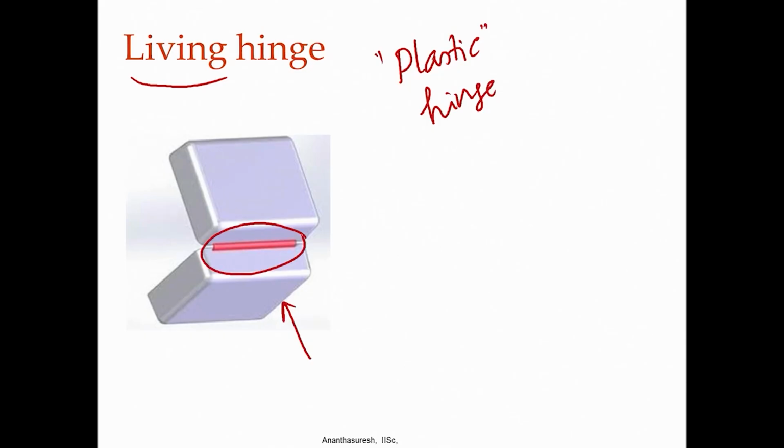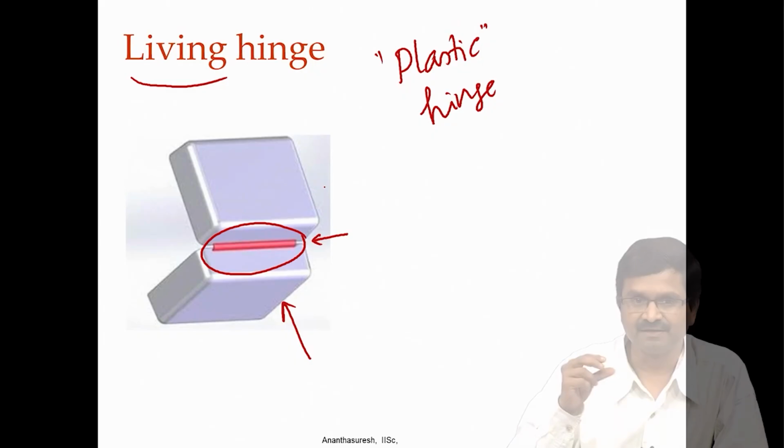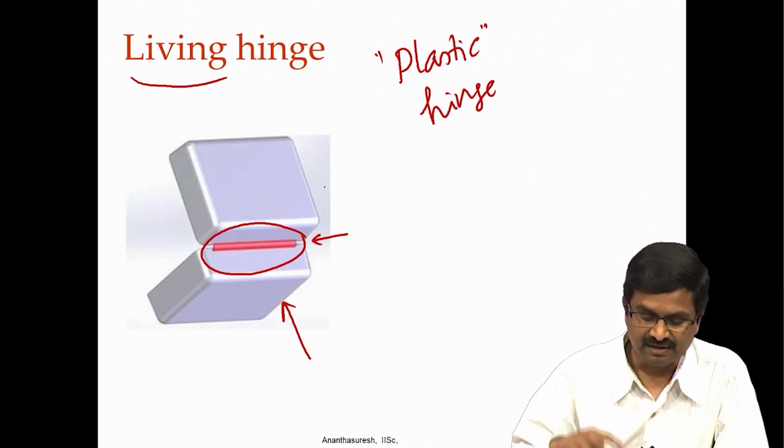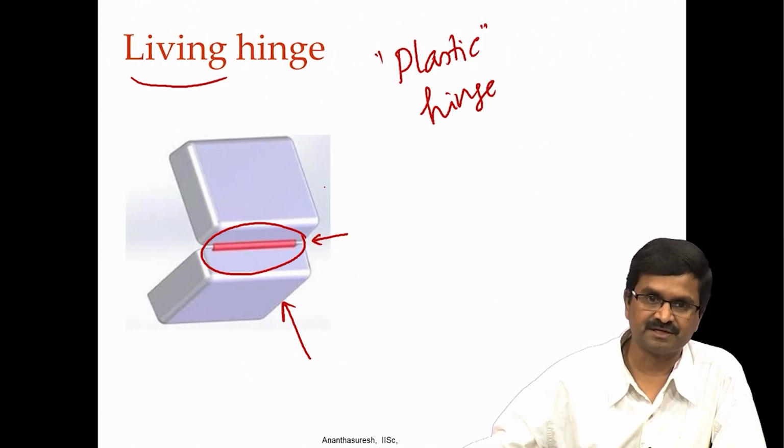And this is the plastic hinge or living hinge, as we call it. Again, plastic, not because it is made of plastic material, but it has undergone plastic deformation most often. Injection molding, people do this specially to make this a little bit more flexible than the rest of the material. You would see when you take plastic boxes, you would see decoloring or slight softening of the color in these portions. There are a number of these things that we see around.